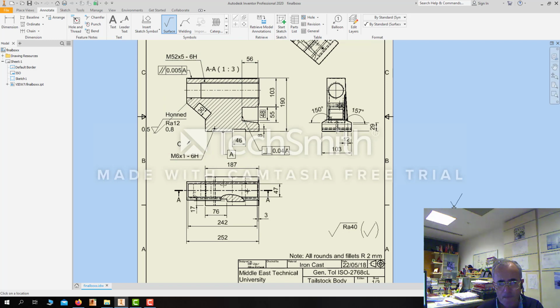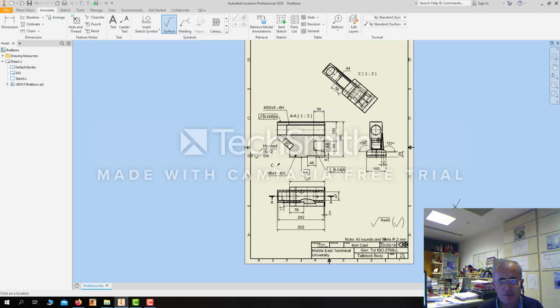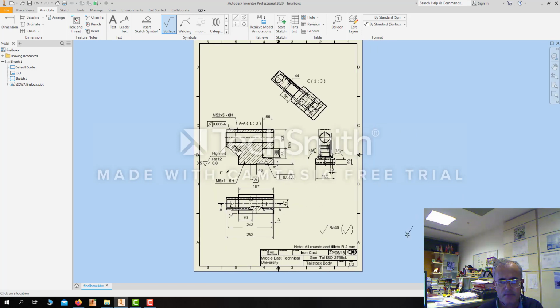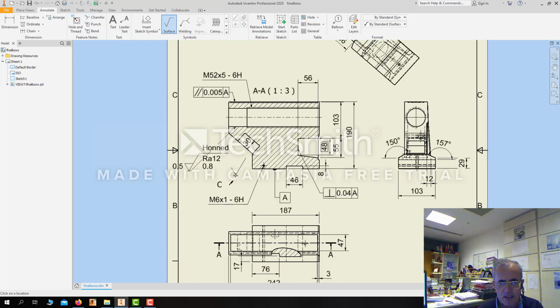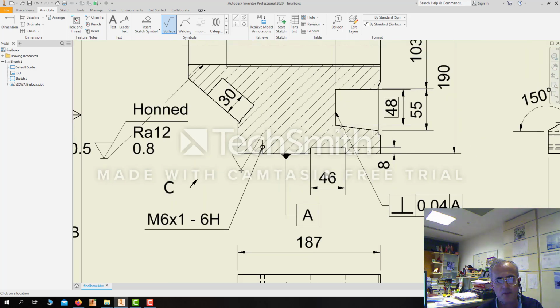This is in the new format. This indication is in the new format of the standard, not the upper corner, the lower corner. Well, along the shoulder, below the shoulder of the symbol, not only the roughness cutoff value but also the arithmetical average value is written, to draw the reader's attention that the number written over here is not the cutoff value but the arithmetical average or roughness height in general.